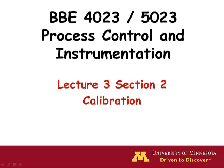This is the narrated PowerPoint for Lecture 3, Section 2. The topic is calibration. More specifically, I will introduce a couple of concepts related to adjusting instruments and a procedure that I want you to use for calculating linear calibration curves using a least squares based procedure.